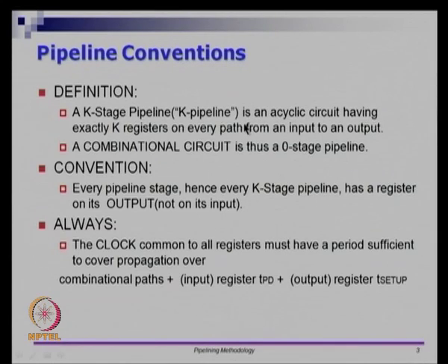So you may have some combinational logic, you may have some registers, you have combinational logic, you have registers, you have combinational logic, you have registers, and so on. You do not have anything feeding back at any point of time. So that is what acyclic means.